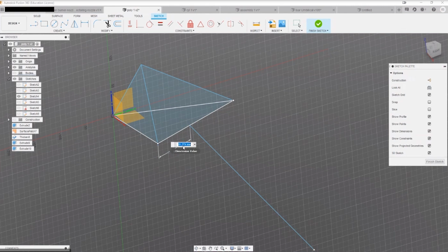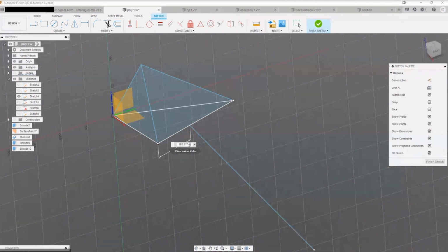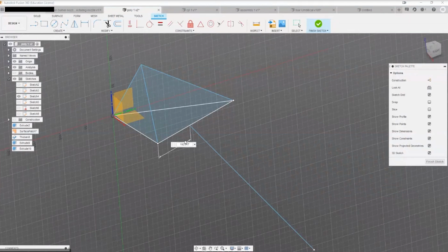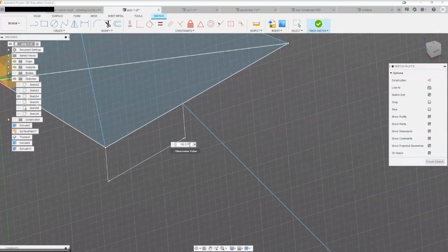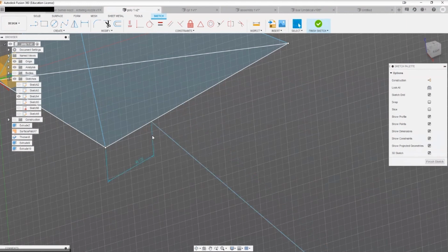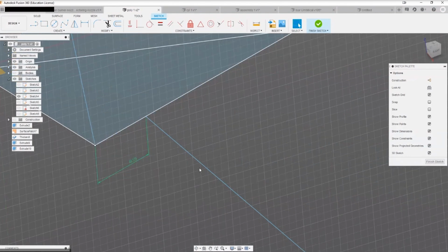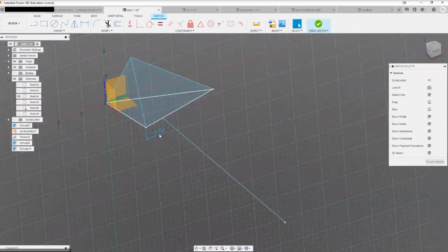Close that and double click in your dimension. Now what you can do is hit Control V, right? Because it was copied to clipboard, it just pasted that out. Get rid of that and type in, you can just multiply it by 0.25. Yeah, so that's a quarter, and that's where it moves out to. So just to reinforce what Robert was saying, that's a really neat trick as well.